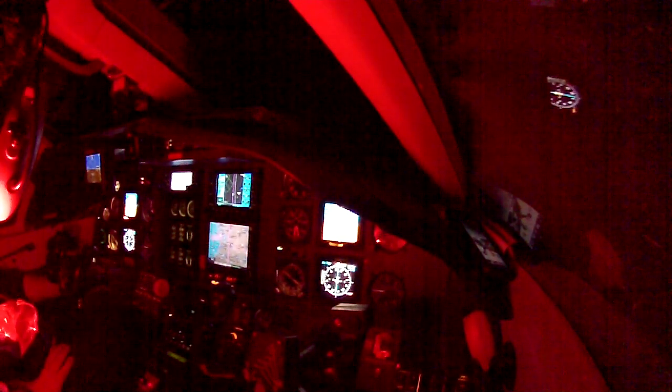Now you ask about, it was a good question. On a regular VOR, you have TO/FROM indication. How do you know with an RMI when you're passing the station? When you pass, it's going to switch upside down. Switch, just like an ADF. It's going to give you a complete 180 and show that the station is behind you. So let's assume we're turning to a heading of 040. After we cross the VOR, it's going to point to 220 right behind us because we passed it.